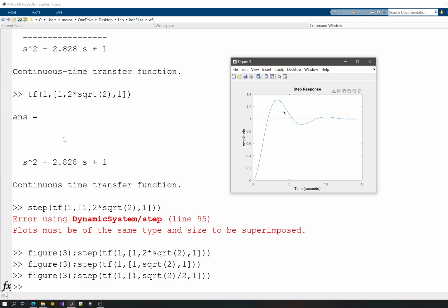By the way, the Ziegler-Nichols method is also not really meant for linear systems, because there are too many tools to design for linear systems. We are teaching it, and we are also preparing questions about it. But the actual usage of the Ziegler-Nichols method is for nonlinear systems. So it is basically a starting point for nonlinear systems, and then you try to tune to get better solutions for the PID controller.